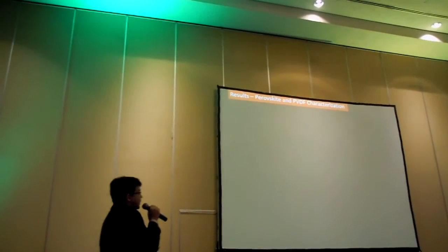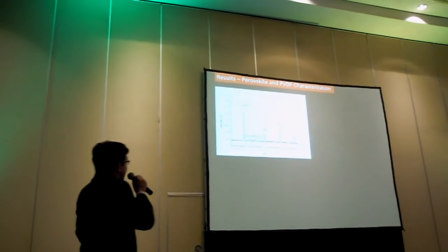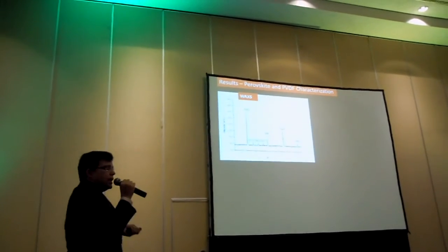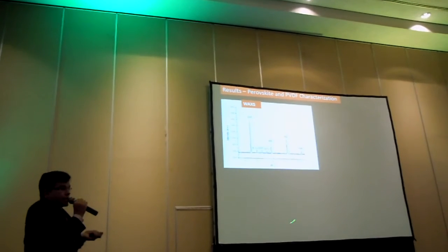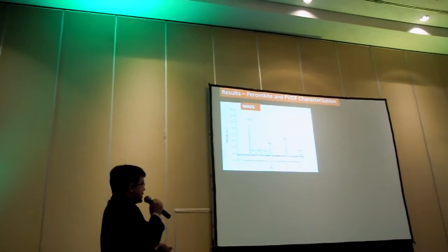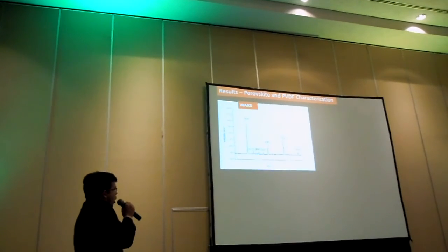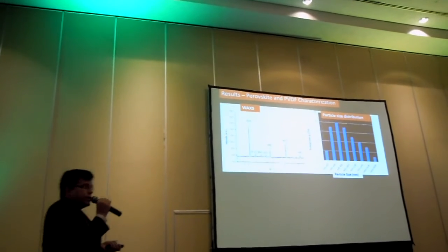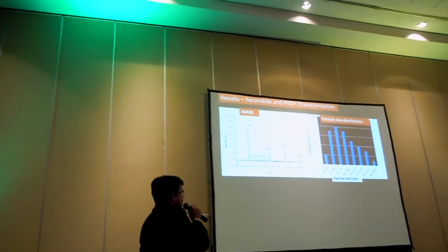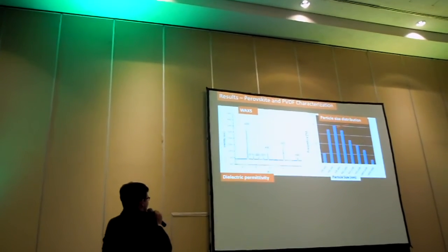Well, now let's talk about the results. First, we made the wide angle X-ray scattering of the powder, and we saw the phase of interest was really obtained. These are the crystalline planes of the ceramic material. We made a particle size distribution too, and we got an average of 700 nanometers particle size.